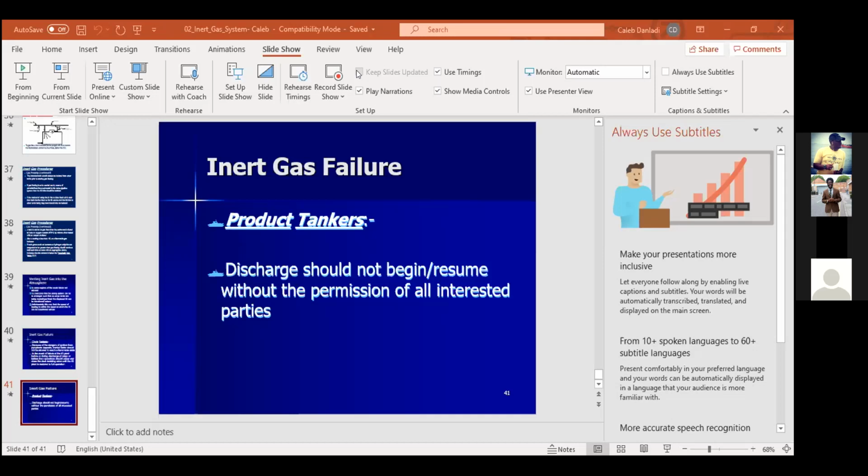The difference now is the one that they are sending you from ashore, from the manifold. So they have to regulate the pressure to your tank, not you. They have to regulate it to your tank. Okay, so you don't have control over the pressure coming from shore. That's why you have to keep communicating. Okay, increase. Okay, reduce. Okay, you can stop. I have sufficient like this.